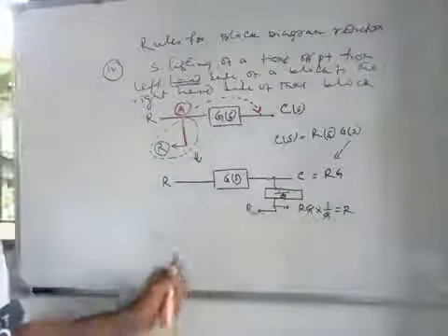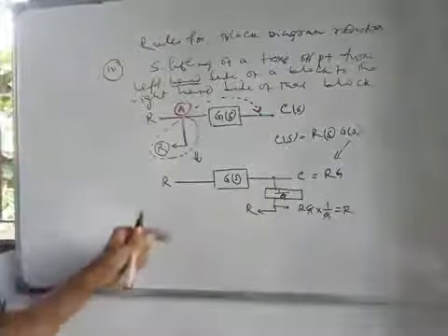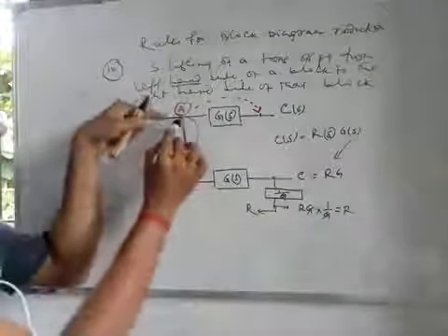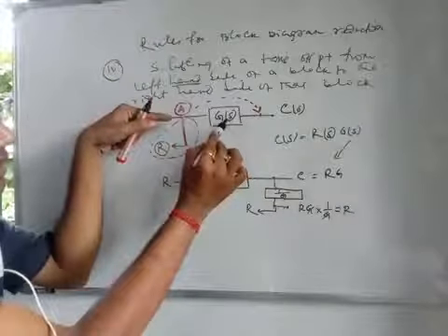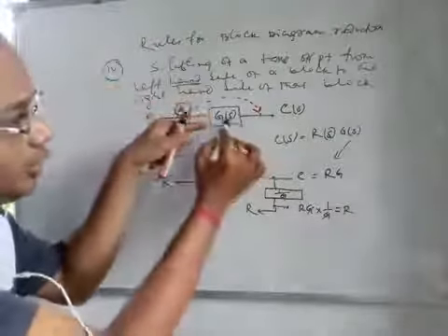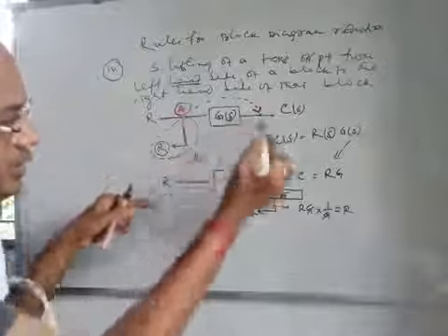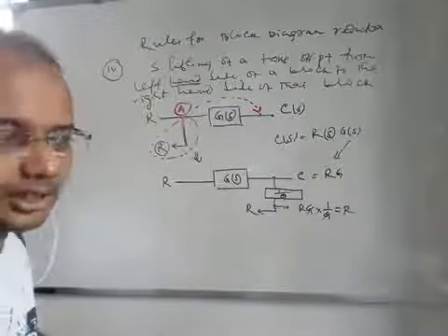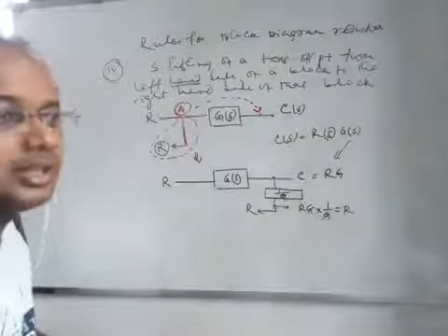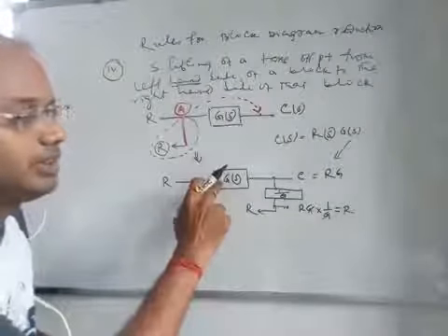So how does it take shape? If any takeoff point is shifted from the left hand side of any block GS to the right hand side of that block, then in this path you have just added the gain, which is the inverse of the gain of the block.